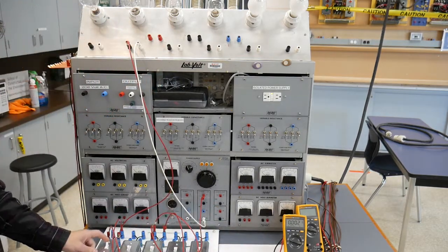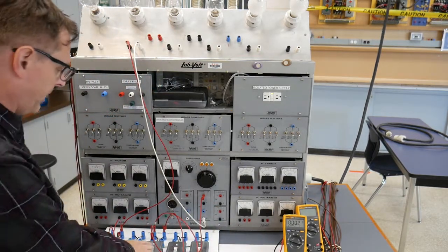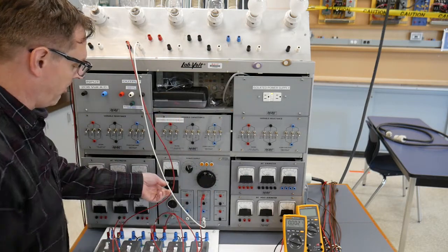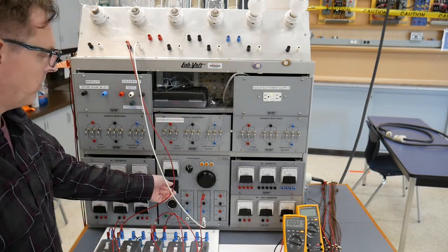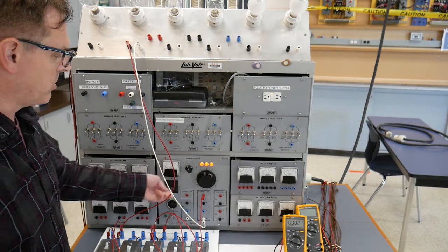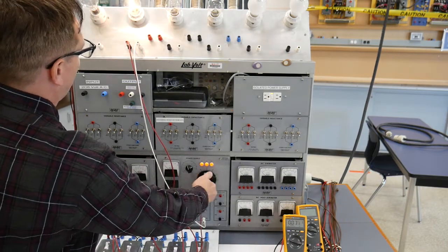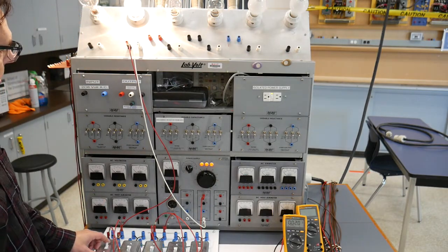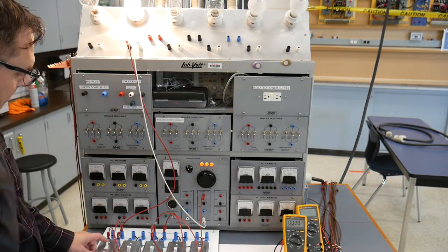Okay, now note that these switches, there's no on or off indication on them. So if I turn the power on and crank it up and the light automatically comes on, it just means that one of those 3-way switches had actually made connection. So turn this on, and we do have that. That's the case. It's a 50-50 shot. So I should be able to control this from both locations.